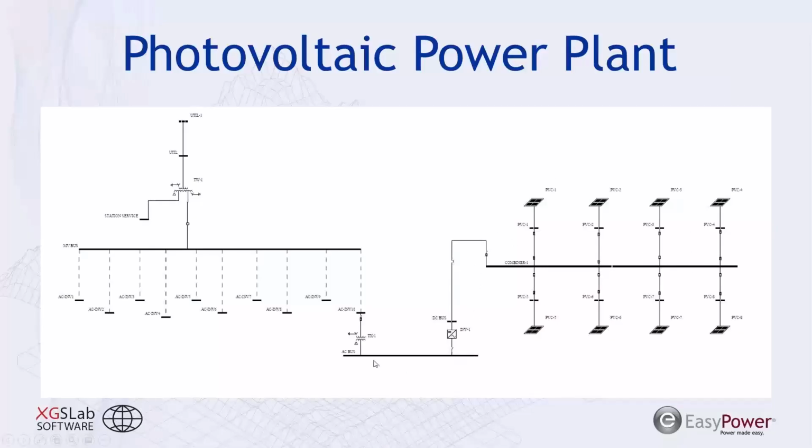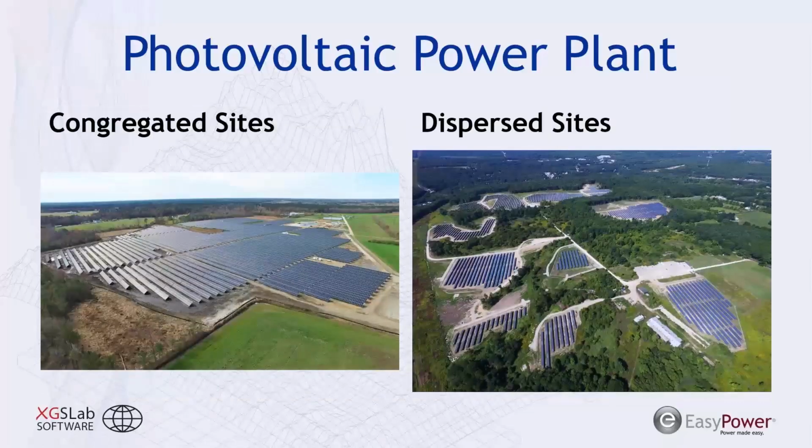They're going to go through an inverter, probably a step-up transformer, or maybe the step-up transformer will convert that to their interconnecting distribution utility line, or maybe you have a Y delta Y transformer with a collector substation associated with this photovoltaic power plant that might step up the energy generated at this power plant to higher voltage levels like 69, 138, 345, etc. But these systems can take several different physical forms.